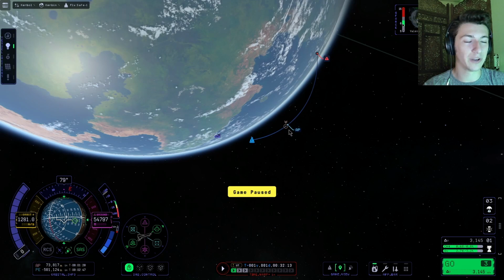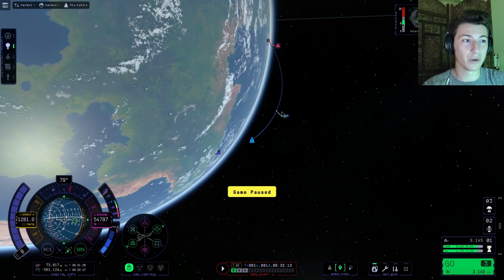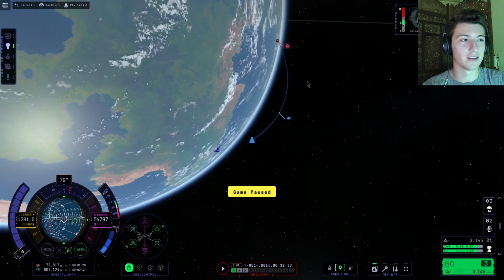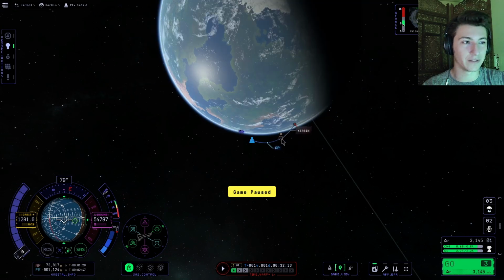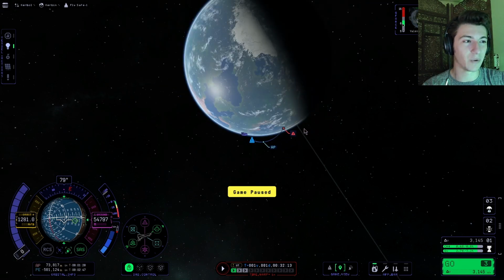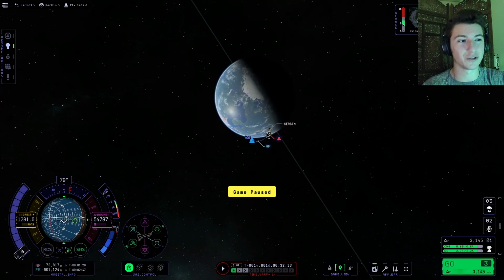And then we're going to orient the craft perfectly prograde. That means essentially pointing this way, like outwards. And then we're going to do a burn right at apoapsis. What that does is it takes this orbital trajectory and expands it outwards so that our craft is going further and further out of the planet until eventually we have, rather than a crashing trajectory, an orbital trajectory.